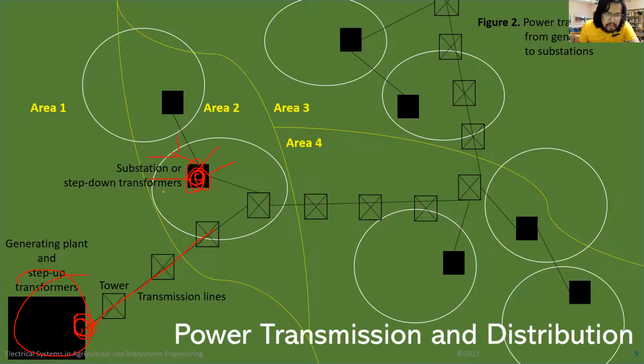Now, to ensure reliability of a power system, nearby subsystems are interconnected. Okay, you can see they are interconnected so that if there's a cut of line over here, there's another line to supply this other substation. This actually allows alternative sources of electricity should that one line or other lines fail.